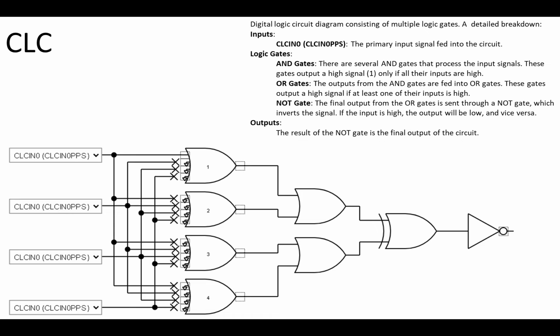We're going to implement a primary input, which is the switch on RA3. We're going to have a logic gate, and then we're going to invert the output to turn my LED on or off, depending, because my input state is different. It's high, and when I push it, it goes low. I just need my LED to be the inverse of that. So I've got an OR gate right the way through, really simple. And we're going to walk it through.